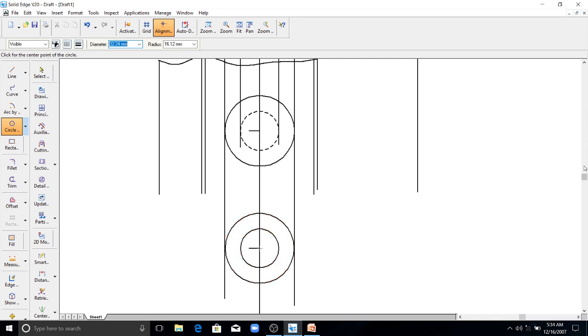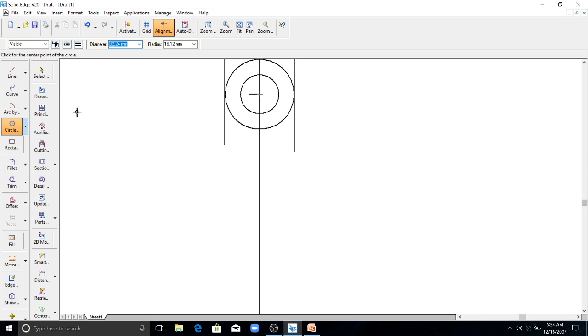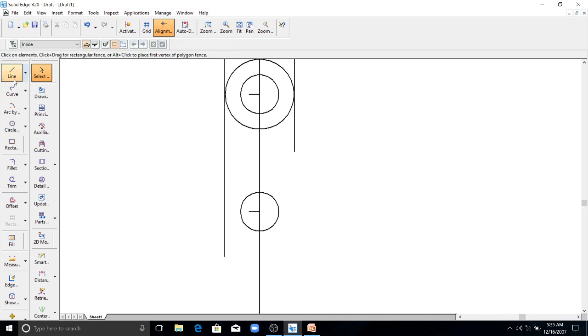Okay. Now the third rivet, again you have to leave a gap of pitch P, that is 54 mm. So I'll offset 54 mm here. Draw 2 circles. First diameter is diameter of the shank, that is 18 mm. Another diameter is diameter of the snap head. I'll project.